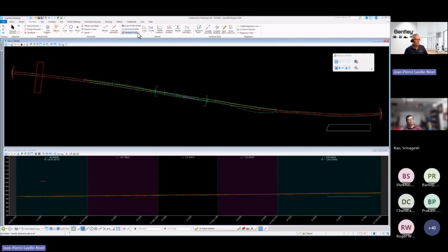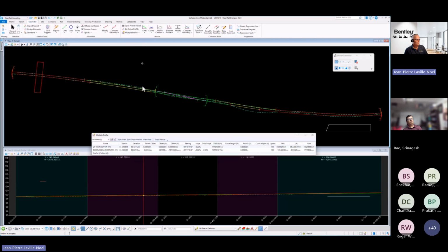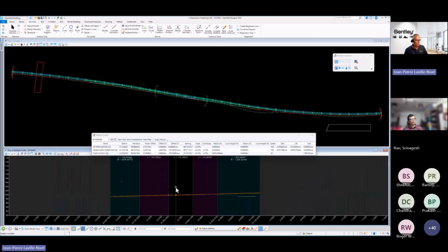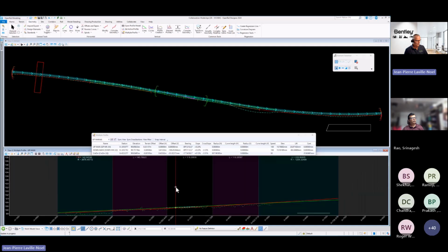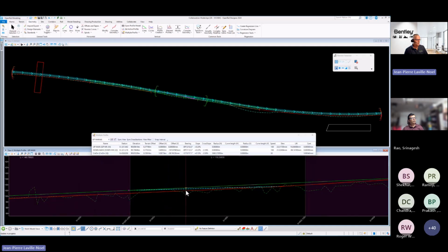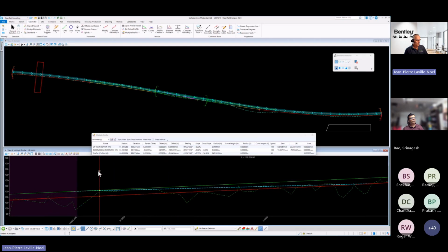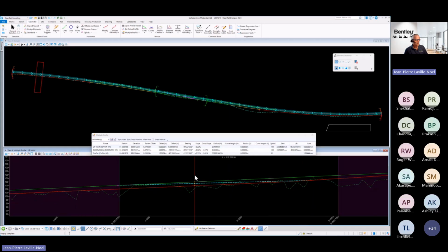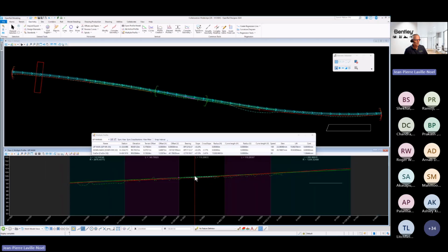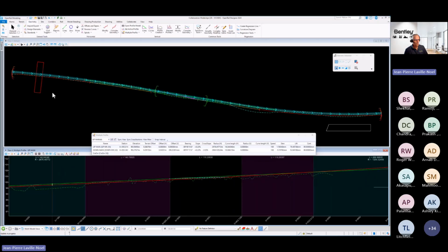When you've got the multiple profiles, you can drag along the profile or the plan, and you can see different information in the dialog from up main, down main, and crossover: station, elevation, offset from the track. The up main is the main, so we have offset 0, bearing, slope, cross slope, speed, slew, lift, cant. So all types of information that we can get in this analysis tool.